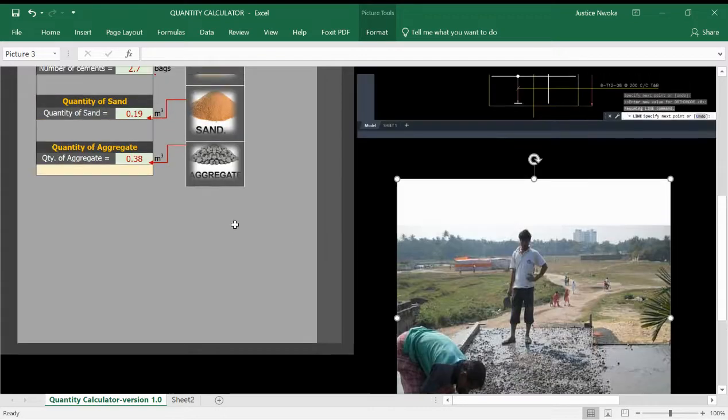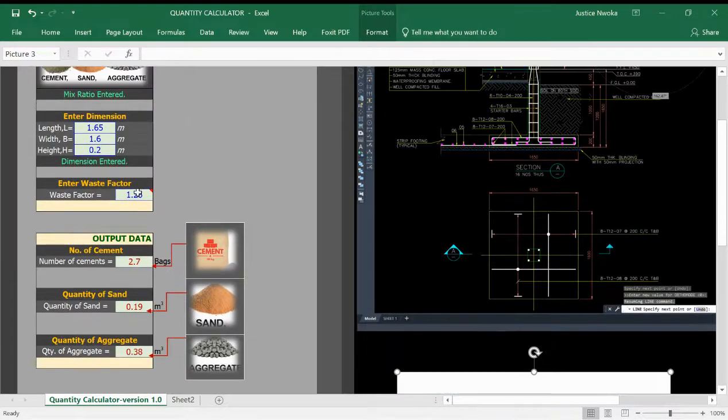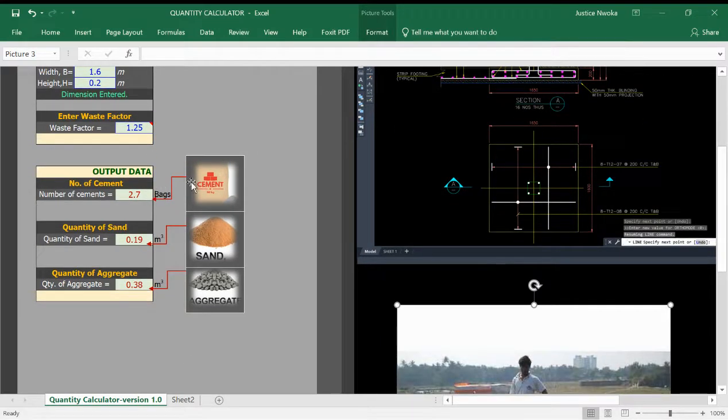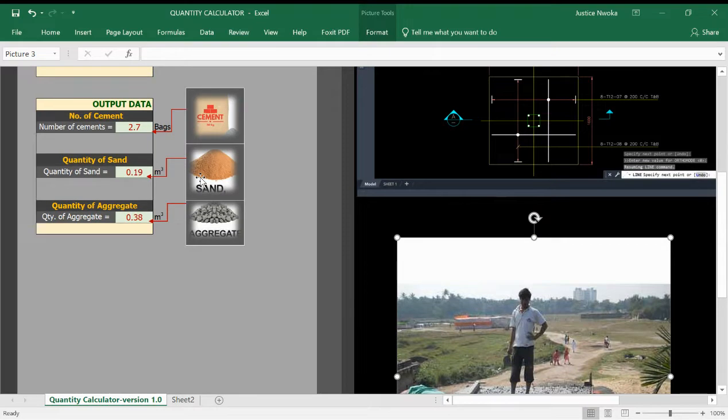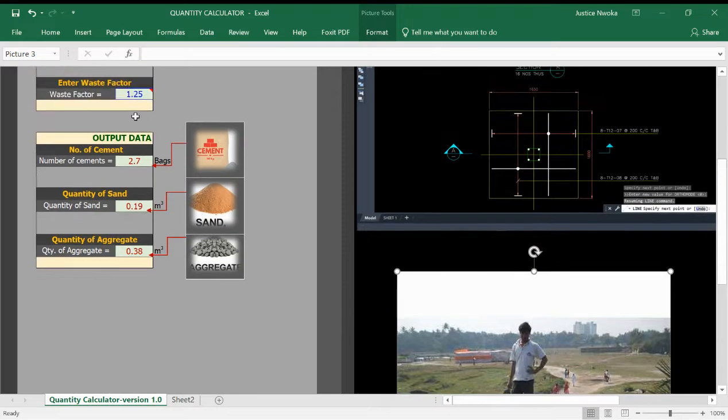So this software gives you the leverage to be able to explain where they will be mixing your concrete, whether it is far or closer. Now, because you are trying to give an estimate to your clients, you have not yet started mixing your concrete. So this software gives you an instruction, as you can see there. Once you hover your mouse on this place, it will show you: enter the value of concrete waste factor starting from the value of 0.5 to 1.4.